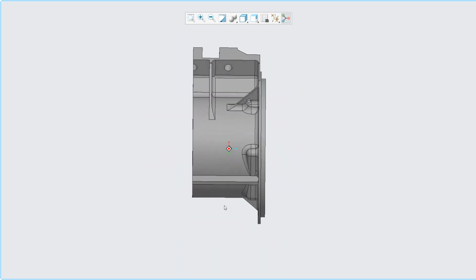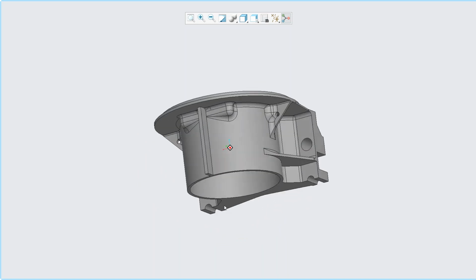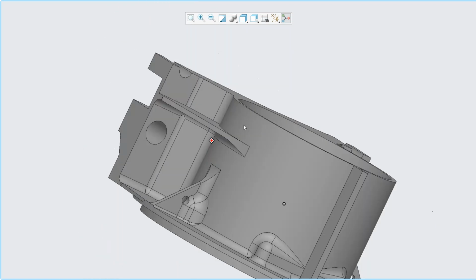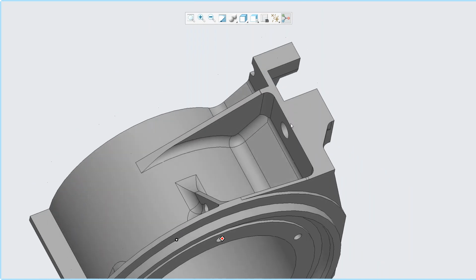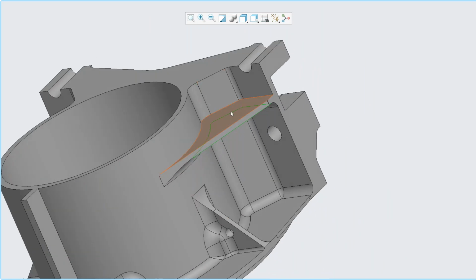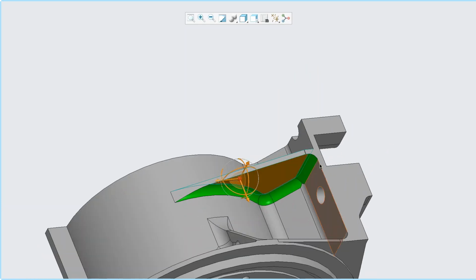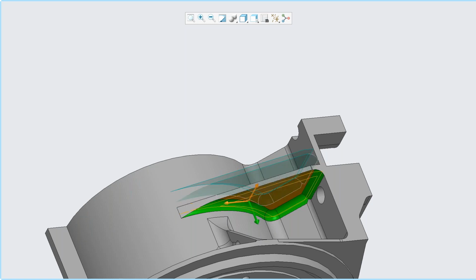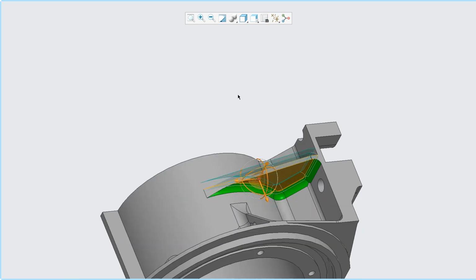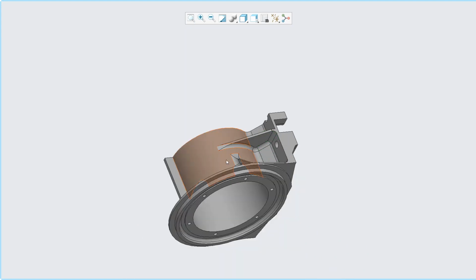Now, let's say I also can do a few more things. Let's see here, this particular design right here, maybe this one here. I would like to select this geometry. At the same time, I also want to select this geometry here, and I can do a move. Now, when I do a move, it is automatically identifying the rounds, as you can see. It found some rounds in there, and as I'm editing, I'm able to give an offset, right? I can do that change in quick time here, do a little preview there. It looks good, and get out of that.